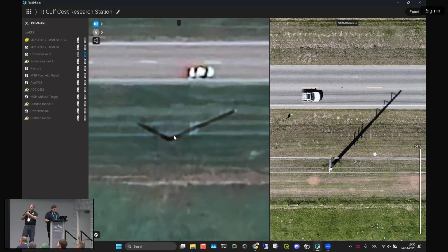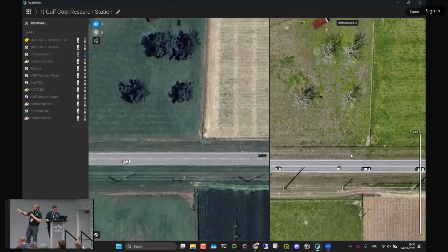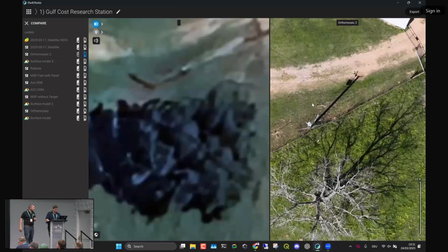We talk about geopositioning and issues with satellite imagery. If you're going to draw your spray boundary for your drone, how close are you going to put your spray boundaries? I'm going to stay the heck away from that, right? Because I don't want to spray that close. I'm not sure which direction it's off, north, south, east, or west, and I'm not sure which direction my drone's going to be off. So see how big of a difference that can make. This is why we're talking about this, and I have a feeling that's a lot of the reason why you guys are sitting in this room too.